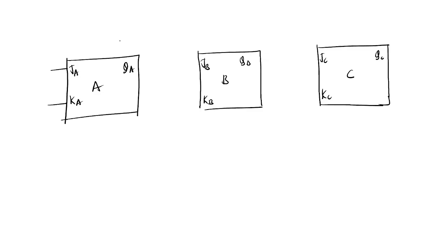A T flip flop means only one input will be there, and it is given to toggle mode. Either T flip flop or JK flip flop. First you need to design the mod counter, the nearest mod of the counter. This is negative edge of the clock, meaning Q is acting as the clock for the next flip flop, and there are asynchronous inputs.